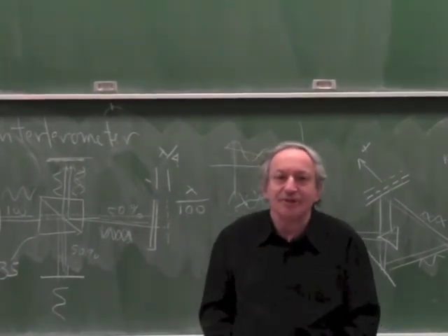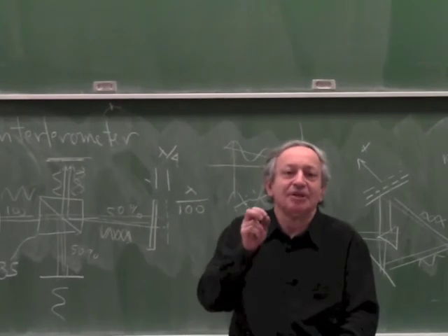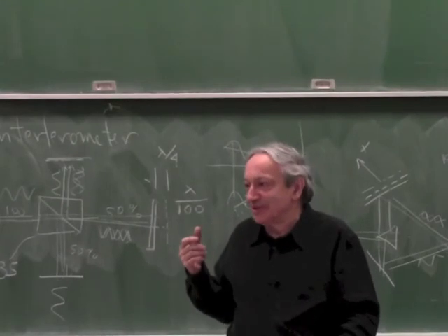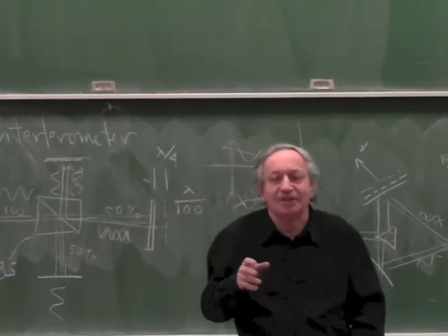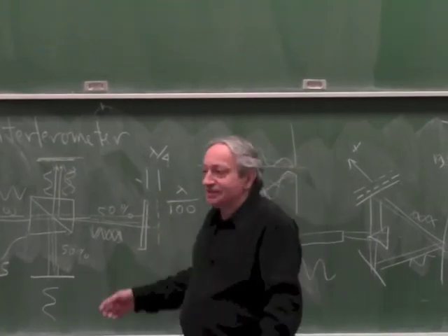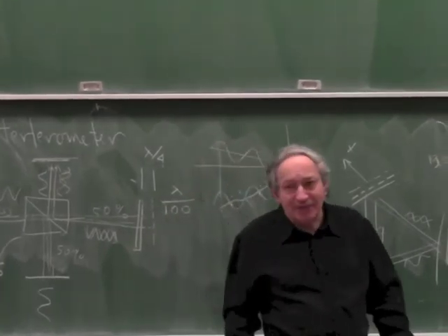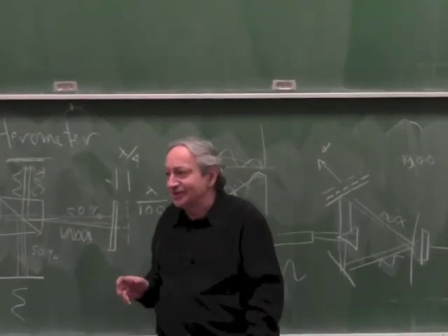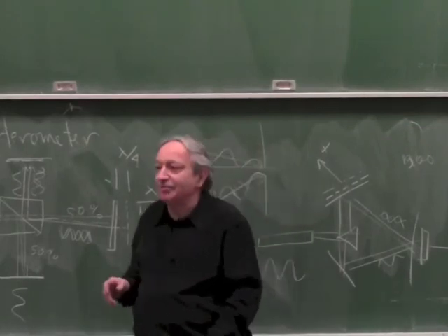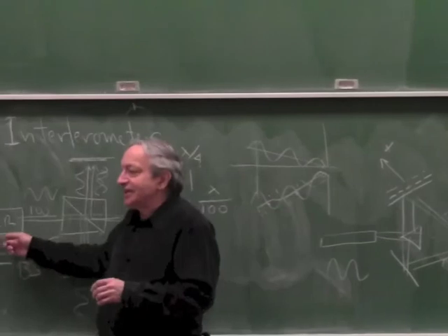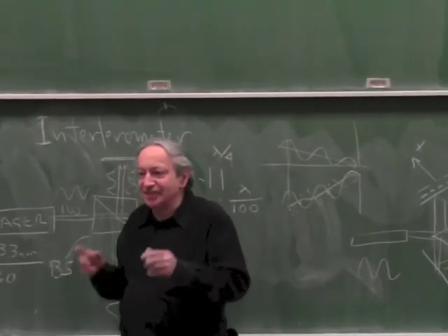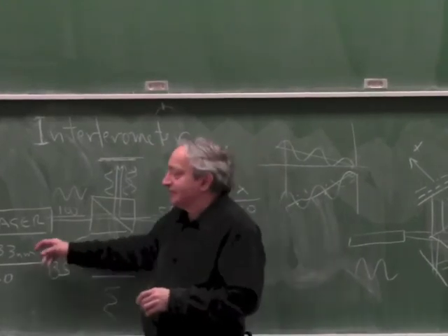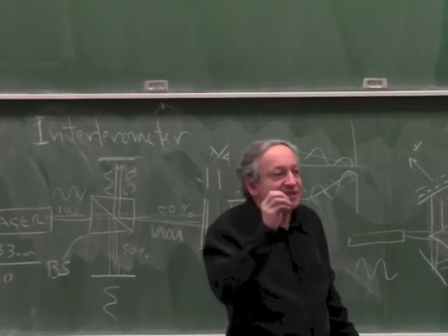But it's a very good instrument to measure from, say, 1 millimeter to 1 meter, because below 1 millimeter there are simpler ways to do it, like a capacitive sensor or an optical sensor. But between 1 millimeter and 1 meter or several meters, that's really one of the best instruments. It's expensive. Typically, an interferometer, unless you build it yourself, costs many, many thousands. And another problem, you can't make it small because it needs a laser, and it needs a gas laser, a very stable laser, so it's big. Like a helium neon laser, this big, so you can't make a teeny sensor out of it.